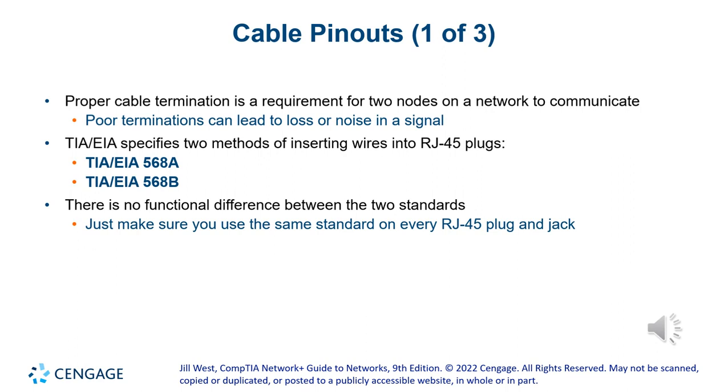Now, to wire the connections from the patch panel to the wall or on a patch cord from end to end, you have to follow two standards, either the TIA/EIA 568A or 568B. They're both very similar. It's just one pair of the cables that is switched. But as long as you switch on both ends, then the cables are exactly the same. There's no difference between the two. The jacks look the same and everything is the same.